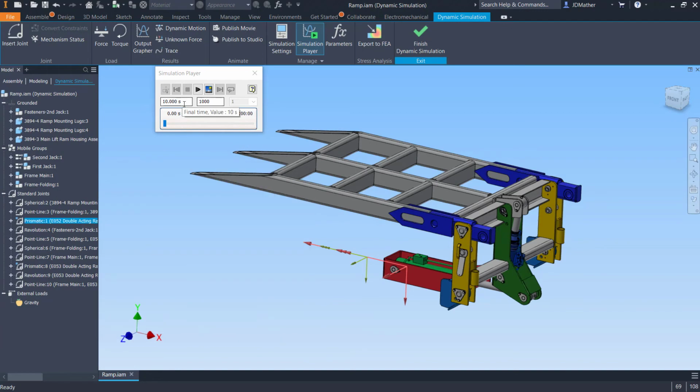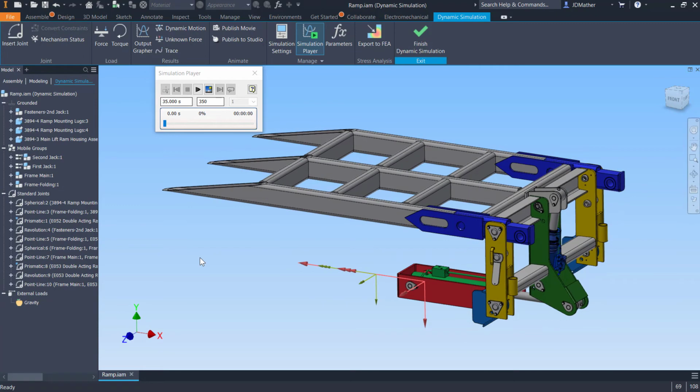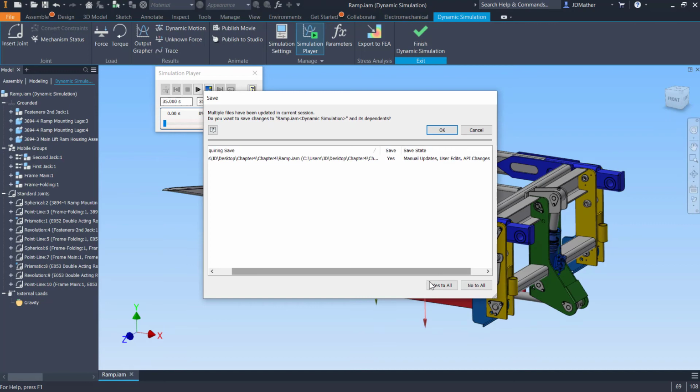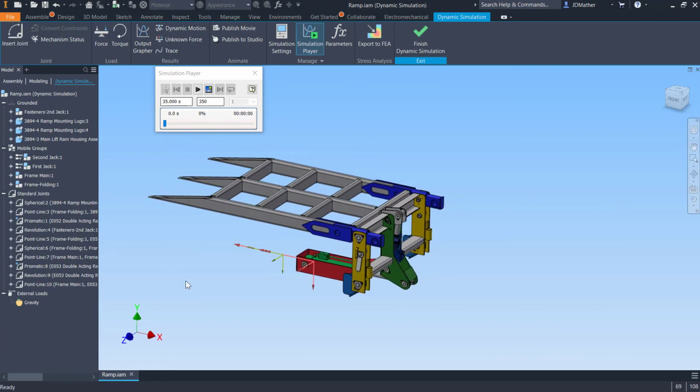We'll increase our time. See, the first 10 seconds is just to open this. It dwells for 5 seconds, and then it moves this down. So let's do this as 35 seconds. I'm going to decrease the number of calculations. Let's say 350 calculations. Again, if it starts moving in the wrong direction, I'm going to stop it immediately. So let's go ahead and save what we have now. Save often.